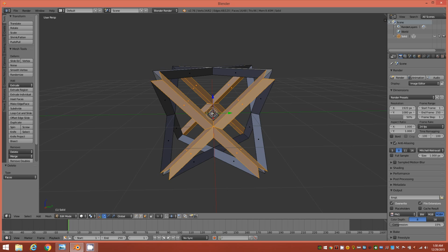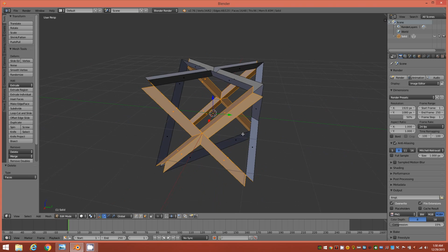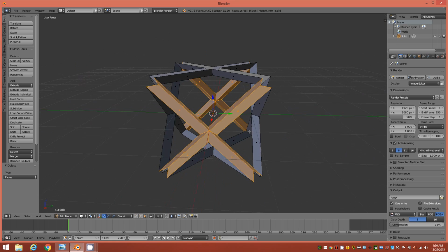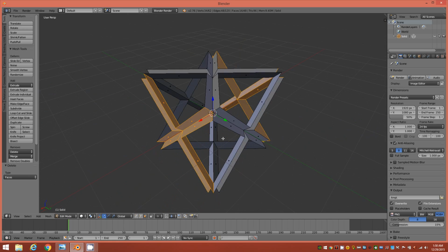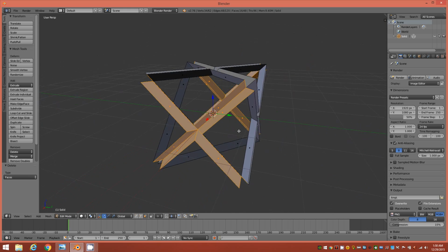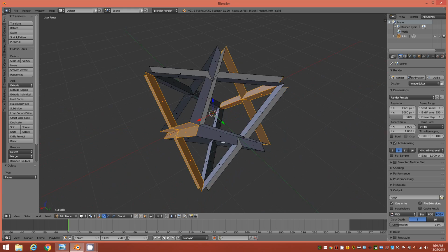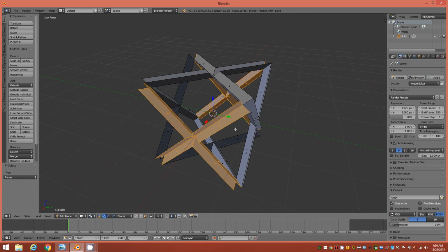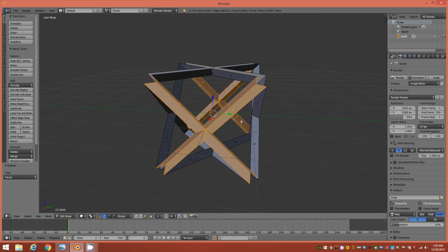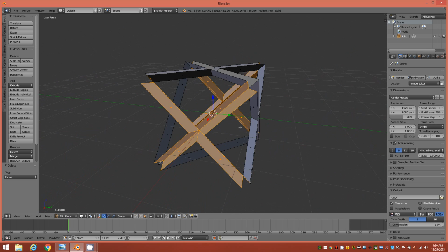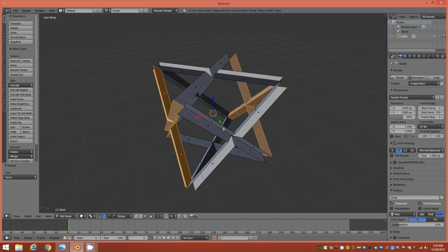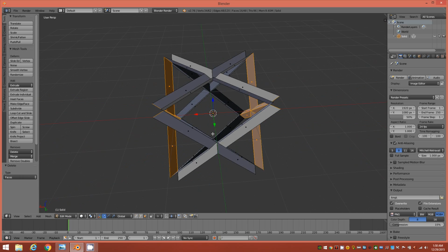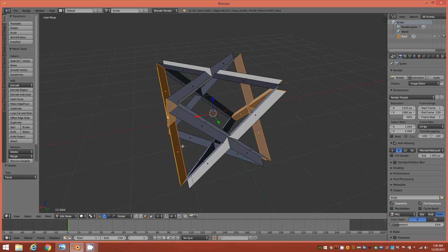Now I'll right click to drop out of the circle tool because we cannot navigate the scene for some reason with the circle tool active, and that's just one limitation that I've come across. I often wanted to be able to tumble around while I still have the circle tool enabled, but we can't do that. So right click to drop the tool, and then you can circle around to make sure you have the faces that you want selected, and it will be these two sides.